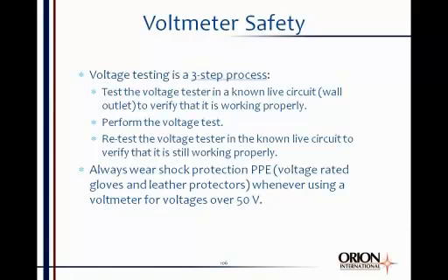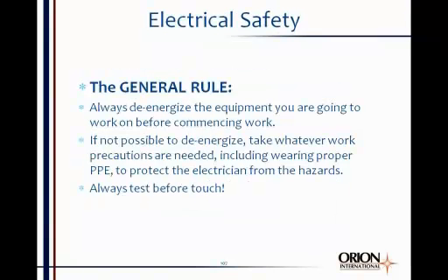This is critical if voltage testing is part of your lockout tagout. You need to know the meter's working properly before you do the voltage test for lockout tagout. So you test the tester, you perform the voltage test, and then you retest the tester in that same known live circuit to verify it's still working. And again, anytime you're working on voltages over 50 volts, in industry now, you're expected to wear shock protection, which is voltage-rated gloves and leather over protectors.